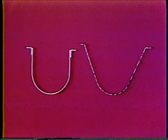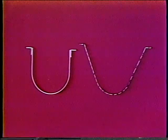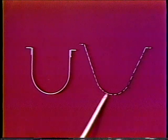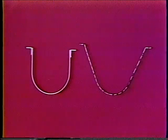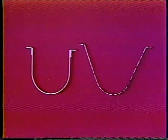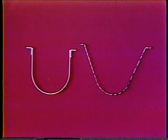The trough is either a U or V shape. If it's a V shape, as you see here, it has a rounded bottom V and may or may not be covered. It is normally fabricated from sheet metal, and if it's covered, it will have a gap in the top for the loading spout. The discharge spout will, of course, be attached to a hole cut in the bottom.